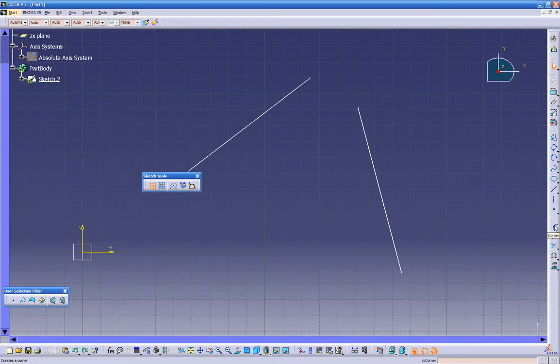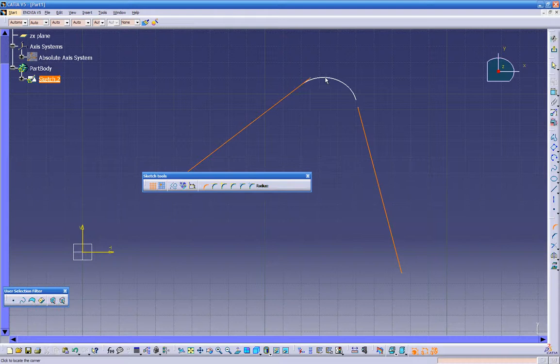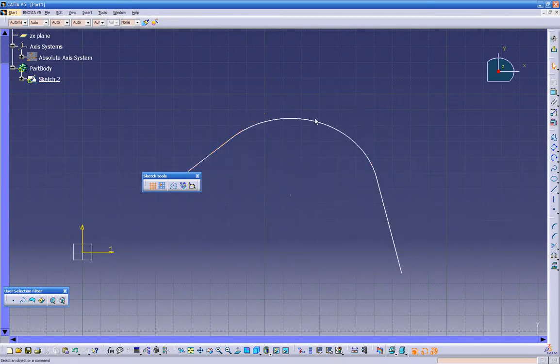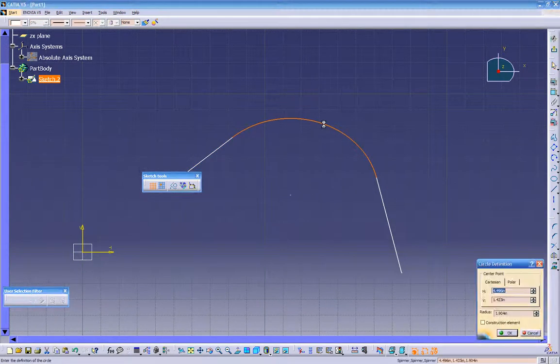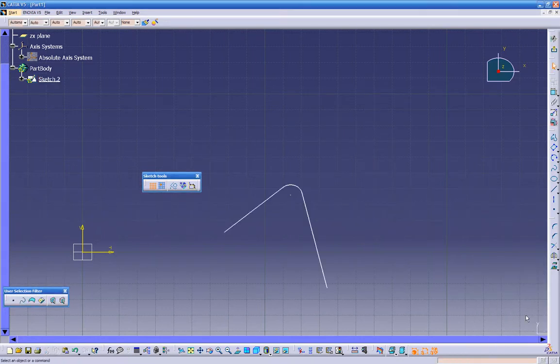on the corner icon. As you see, you have different kinds of radiuses you can create. Click on line number 1, number 2. You can put it anywhere you want, but you can go back anytime later on. Just double click on the corner radius, and down here we can change it to 0.250. See, that's the difference. If we do that, it moves the line. So if we do Ctrl Z, we can undo it, and we can do right click